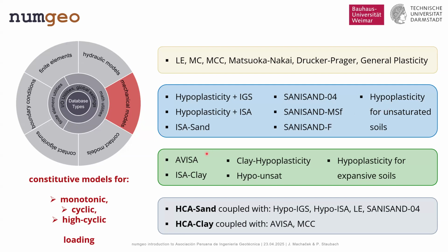For clay type soils, we have another set of constitutive models implemented. For example, the Avisa model by Merita Tafili, the ESA clay model, the clay hypoplasticity by David Mašín, and again a hypoplastic model for unsaturated clay type soils, and a hypoplastic model for expansive soils.